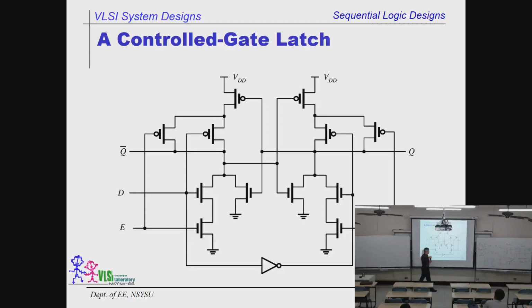And this one could be considered to have the function at least. But the thing is, you only add 1, 2, 3, 4 transistors and you can get it done. Here, if you only add this function, you need 6 transistors. 1, 2, 3, yeah, 6, and 6. You need 12 transistors, because it's a NAND gate and an inverter. That's 6 transistors: 1, 2, 3, 4, 5, 6. You need 6 on top, 6 on the bottom, whereas here you need 4 transistors. It's much more cost effective.